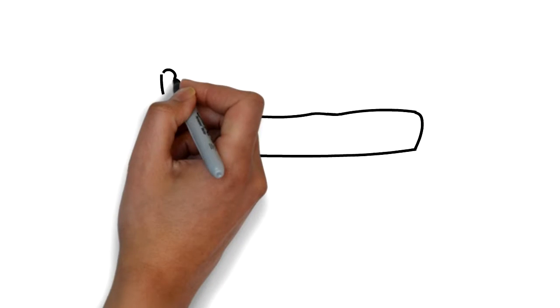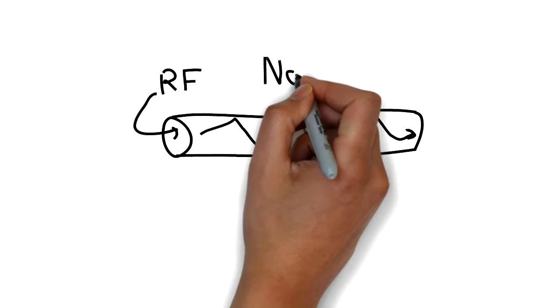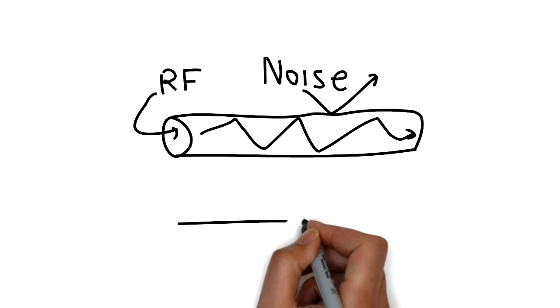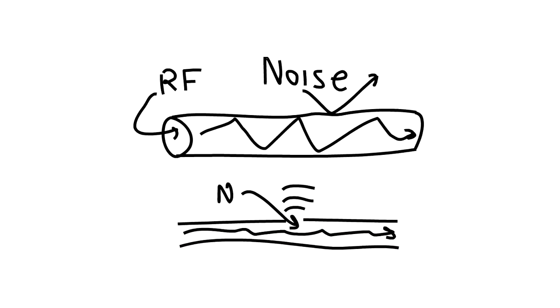Our startup product design understanding of the transmission line should be twofold. One, transmission lines help keep the signal from escaping during transmission. Ideally, all the power sent into the line will arrive at the far end. And two, unwanted or spurious signals will be prevented from corrupting the signal we are sending into the line. In this way, a transmission line is like a pipe that keeps desirable signals in and undesirable signals out. If we have a poor transmission line, then we'll have two problems. Our signal will leak out and noise will leak in.